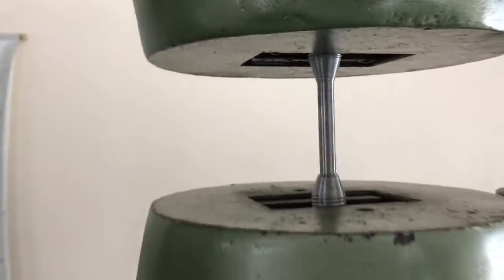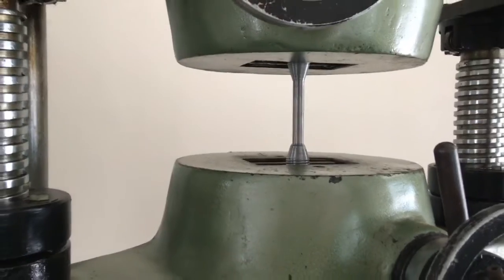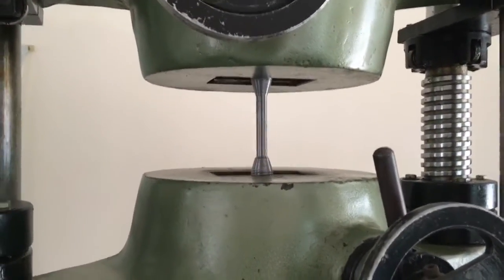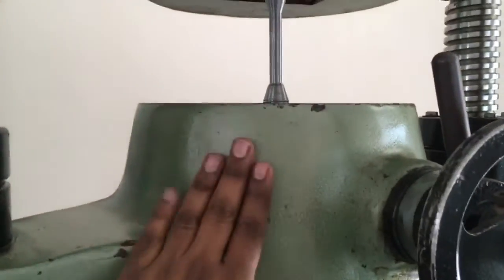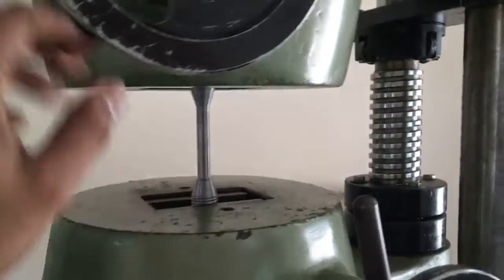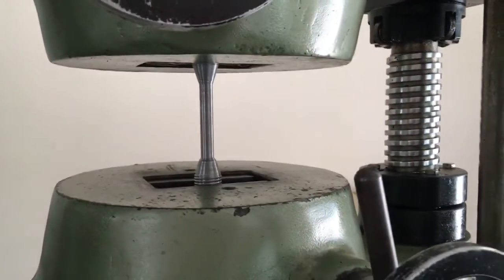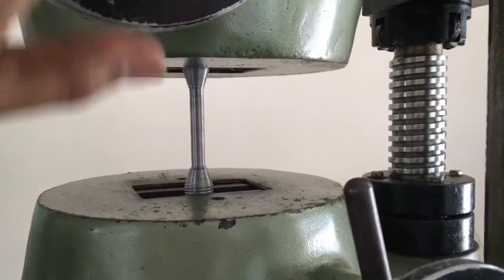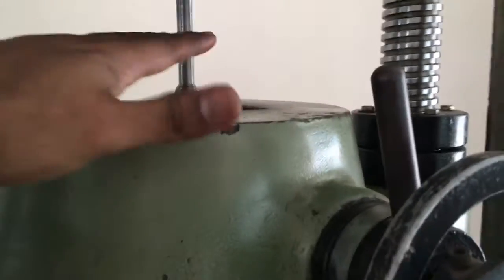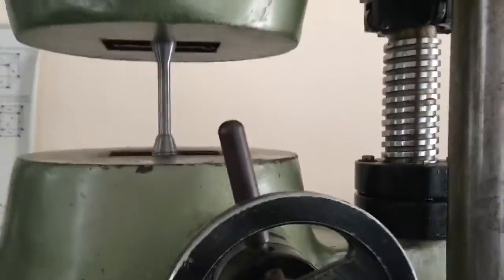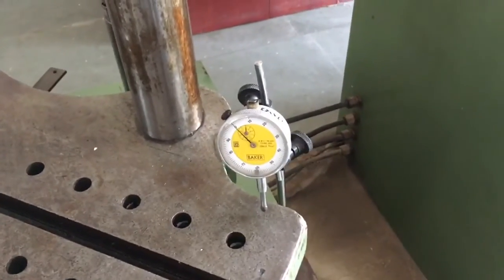Now, as you can see, it is fixed between the two jaws of the universal testing machine, and here we fix this jaw and we move this jaw in upward direction, or basically after we load it, this jaw gradually goes on moving in upward direction so that this specimen is loaded gradually. And while the loading happens, the deformation is measured by this extensometer which you are seeing